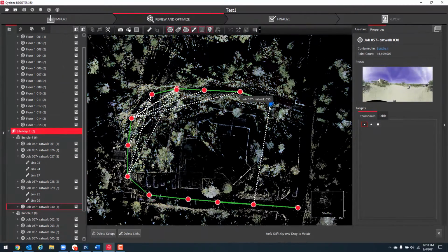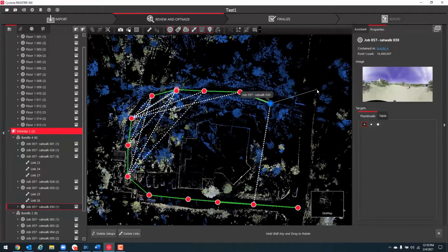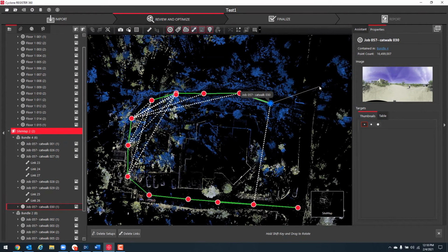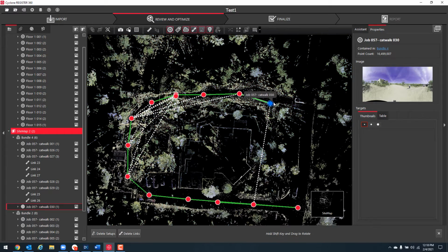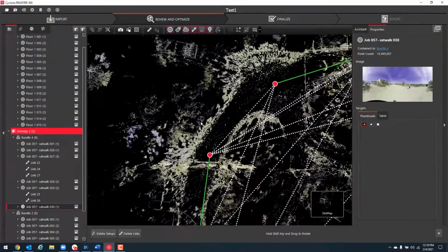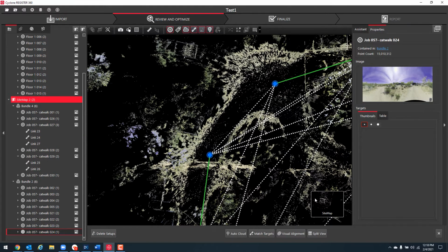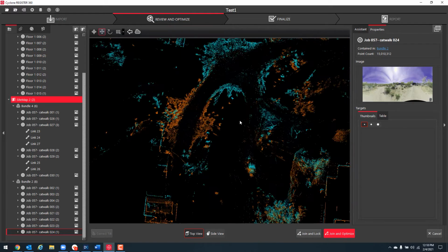The way I'm going to do that is I'm going to click on a setup here, hold down shift, and that line's going to come out. So I'm holding down shift and I'm holding down my mouse. I'm just going to rotate that until it looks like it would get close enough, and then align it. And I could click on this assumed link here, and it'll give me those same options, but I just use the same method each time.